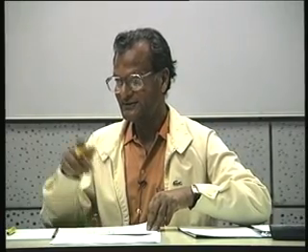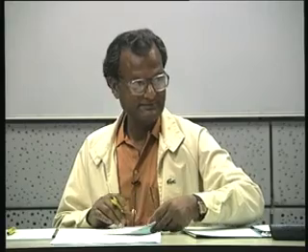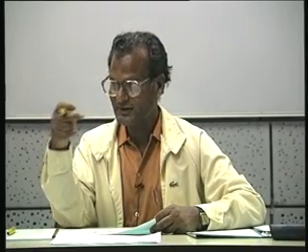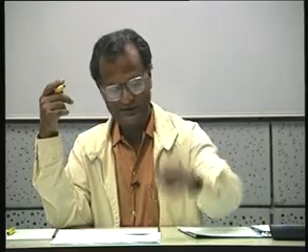You have a question? Okay. Sir, this relationship is for this particular? No, for any, even in the parallel LC, Foster 1. In Foster 1, the product of the two, inductance and capacitance, shall be 1 by omega naught squared. That is a verifying feature.